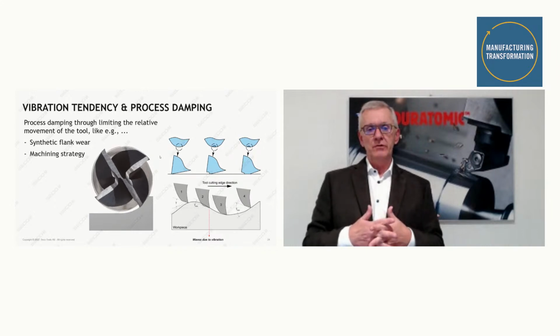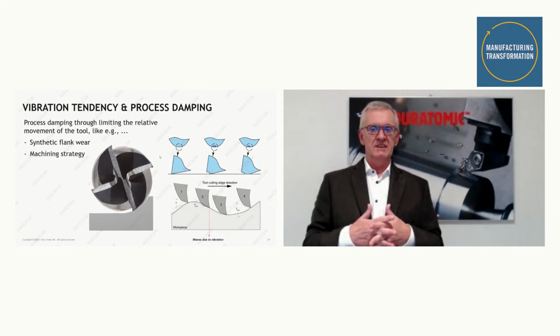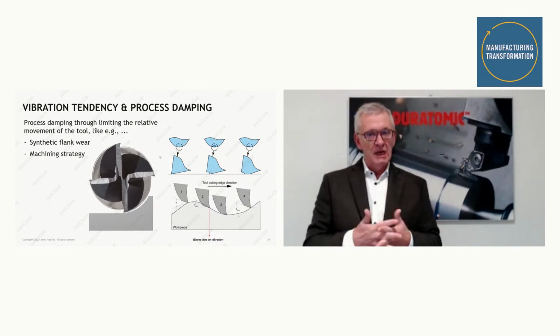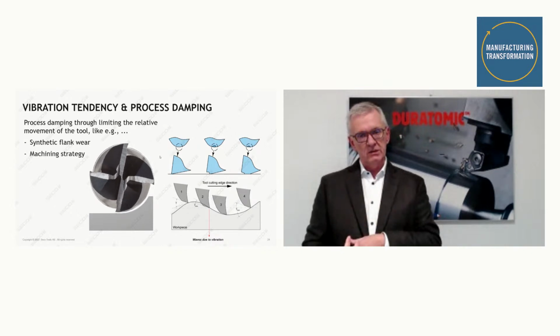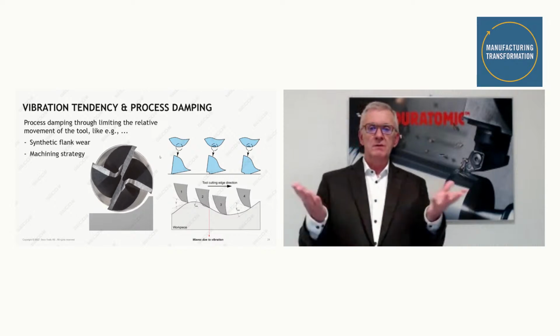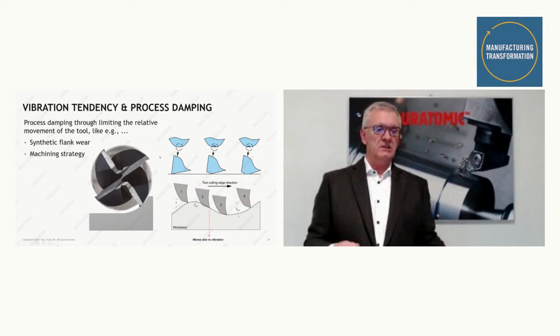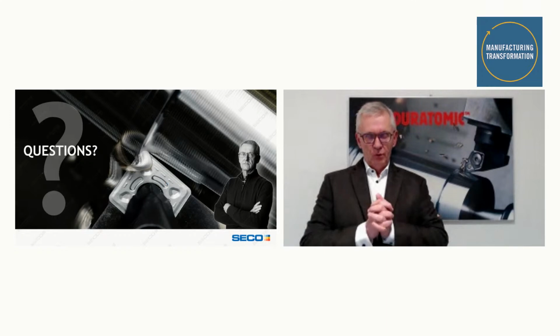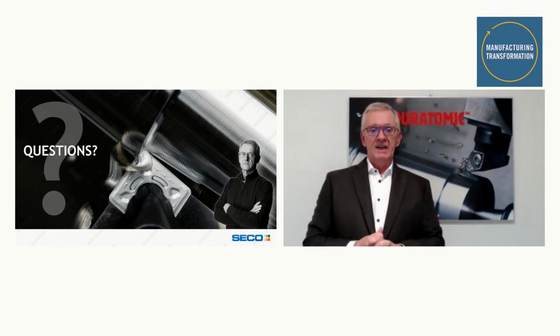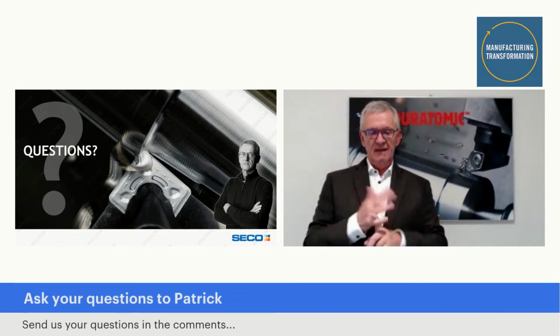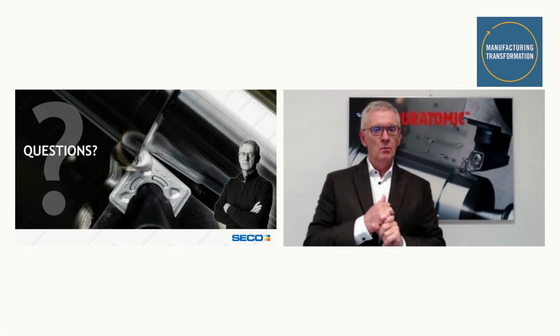In doing so, we minimize variations in cutting forces, and in minimizing variations in cutting forces, we minimize the risk for micro vibrations. Now, it's easily said. I do know it's not always possible. But anyway, micro vibrations is something we have to watch out for because it's sneaky. You don't hear it, you don't see it, but you see the consequences.